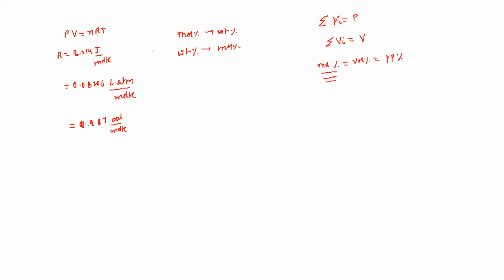All right. Then we studied how to convert something from mole percent to weight percent or from weight percent to mole percent. In order to convert from mole percent to weight percent, we have to take a basis of 100 kilomole of mixture.